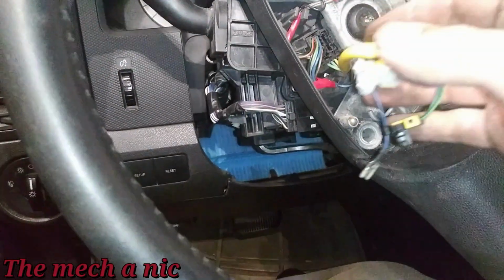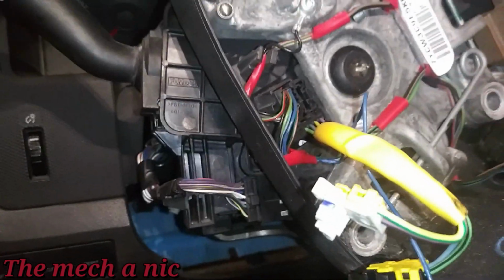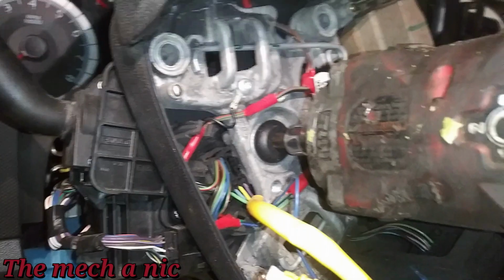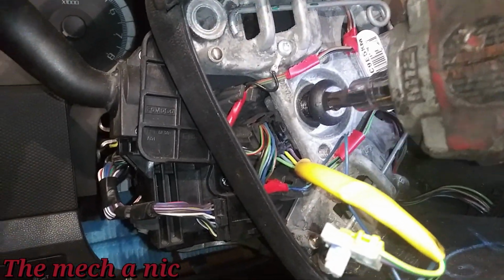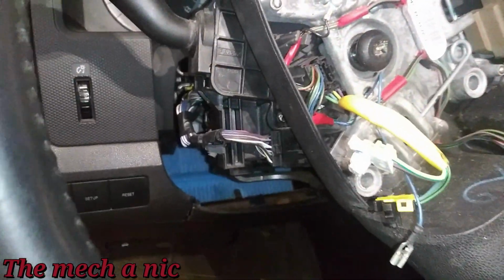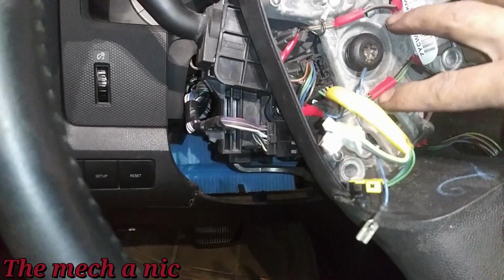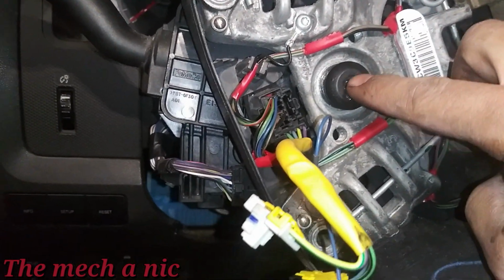All right, so once you get the airbag out of the way, we're going to go ahead and remove this center bolt, which is a T50. Ideally, you want to use an impact gun for this. See how easy that comes off? Now the trick here is you're supposed to use a steering wheel puller, which would thread into both of these holes right here, and then you press off of the center bolt.